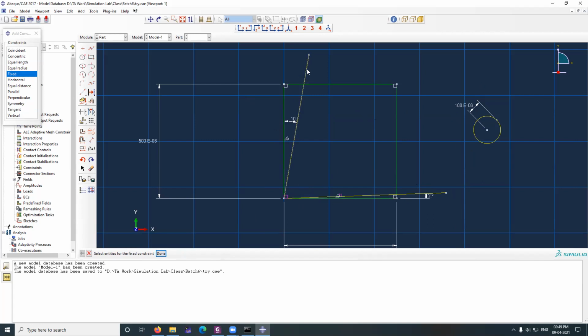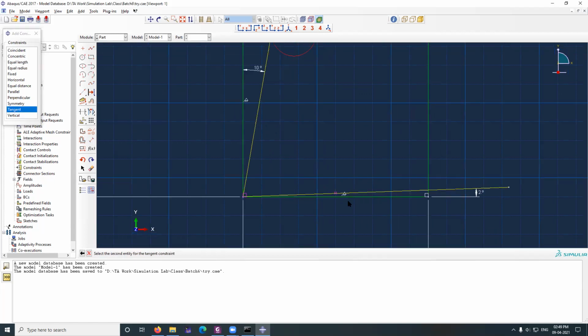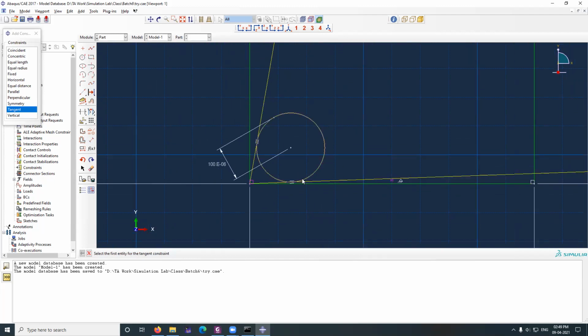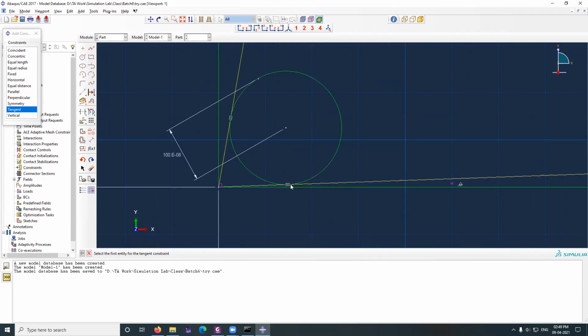And again, these lines are constant to these lines. So this setup won't move. Okay. So now this will move to this place. Let me choose tangent, click this one and click this one. See, now it has moved. The other case also fine, but I'm comfortable with this one. That's why I'm doing like that. Again, click tangent, click this one, and carefully choose the second line. So you can see it here. Now it has become tangent. Okay, tangent to the new line.